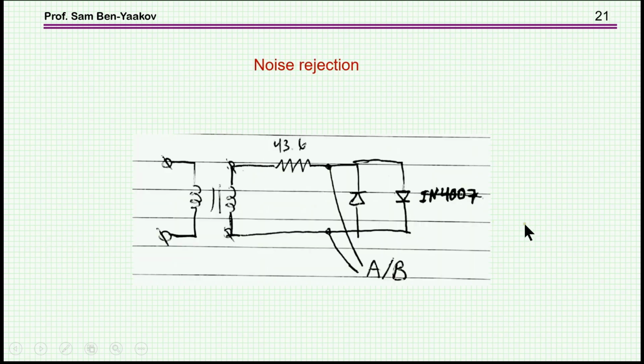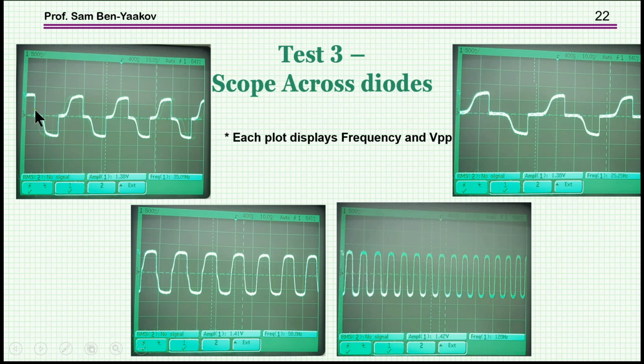So what we did is the following. We have set up a test circuit that looks like this. These are two diodes, and then we have the injector, so we have an excitation, and now we put A and B over these diodes. So we look at the ratio between A and B. Now, to do this and to get the value, the analyzer has to be able to extract from these waveforms. These are the waveforms that we see here at different frequencies. That's a lower frequency, and that's a high frequency because the capacitance looks like that.